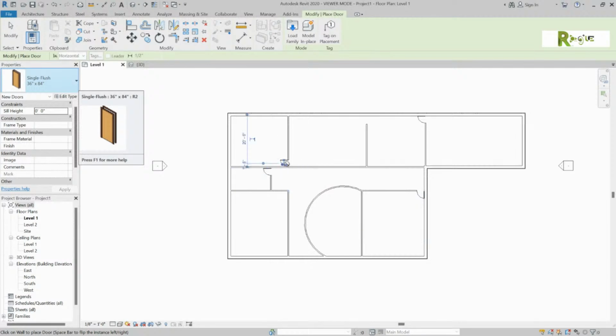And typically we would never put those right up against the wall like that. You got to have enough room for a double jack, a double stud, because you need a jack stud and a king stud at the door. So you would typically be 4 inches off, 6 inches off, whatever somebody would like. Once again, we're going to show you how you can actually set that in one of the later classes.